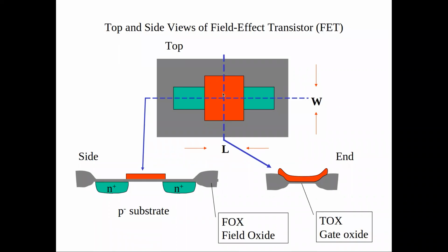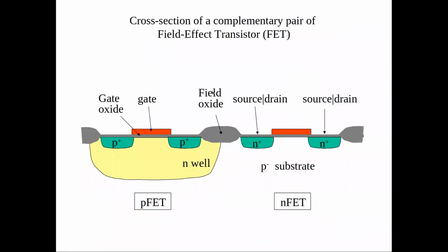Yes? In the last slide, what's the field oxide for? The gate oxide is this very, very thin insulating layer that is insulating the semiconductor from the conductor. The field oxide is the same. It's this SiO2, silicon dioxide. It's just that it's not controlled by the masks. It's allowed to grow. And so the part of the oxide that is not thin is called field oxide.